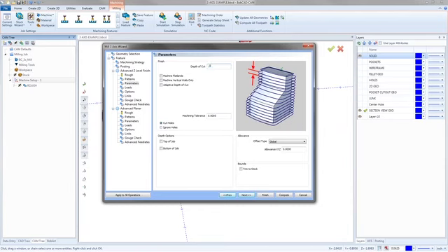Depth of cut, like I said, I have numbers that I use for everything. These numbers will change for you guys when you're cutting your parts, but I recommend having some numbers where when you start thinking you're on your finishing, throw a 50 thou in there and compute it. It's going to compute faster than your probably normal finish of 10, 20 thousandths or whatever you normally do, but it'll give you an idea if you're even on the right track.